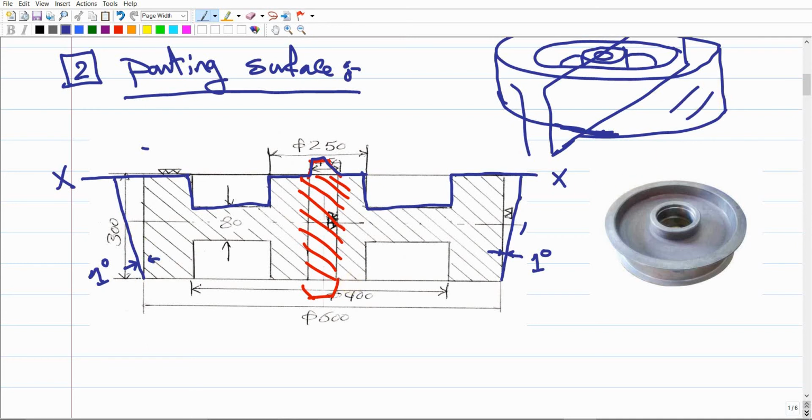It means that this cylindrical surface of the product will not be vertical. Instead, it will have some taper here. It will be tapered somehow from both sides. It means it already has a conical shape opening up, right? So if we apply this taper or draft allowance to the pattern, which of all of these dimensions would be affected by the taper?